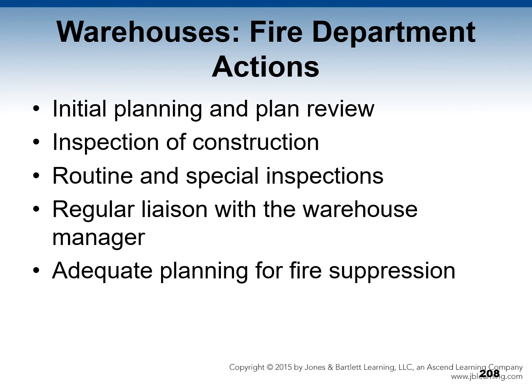Fire department actions at a warehouse fire. Of course, pre-incident planning needs to take place, and before construction takes place, there needs to be initial planning and plan review prior to that construction. And inspection of construction and witnessing of fire protection equipment tests needs to take place. Routine and special inspections during operations need to occur, and there should be a regular liaison between the fire department and the warehouse manager.